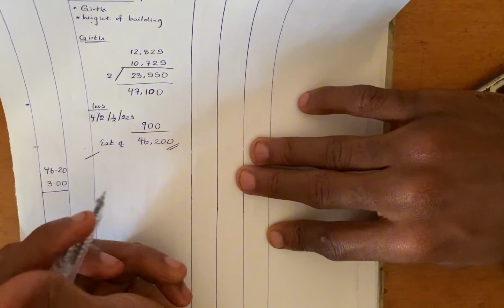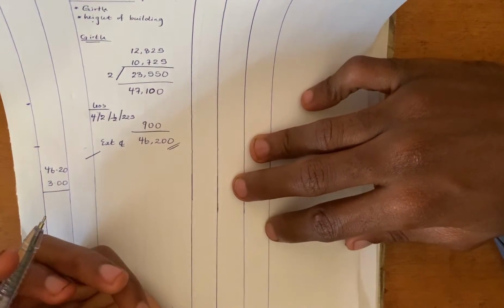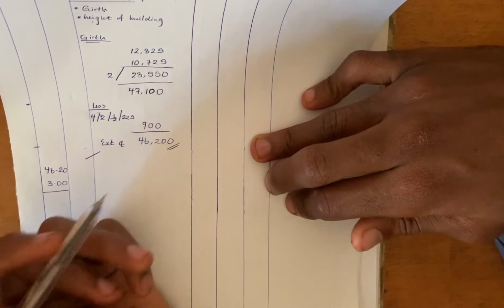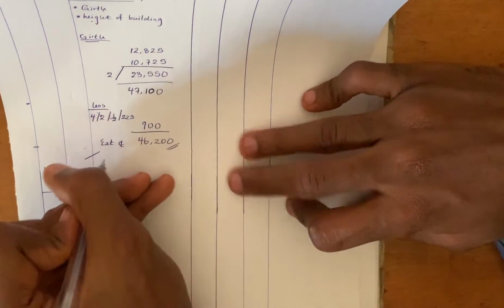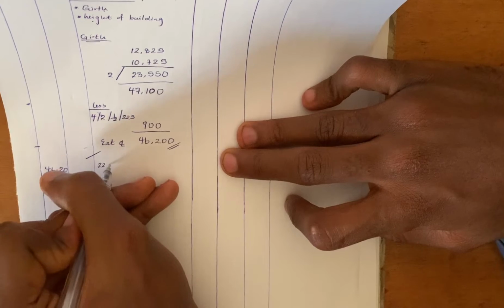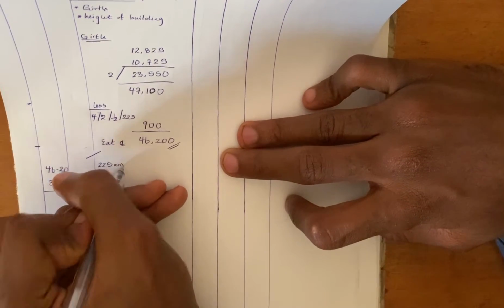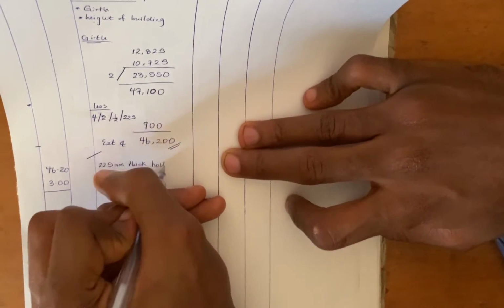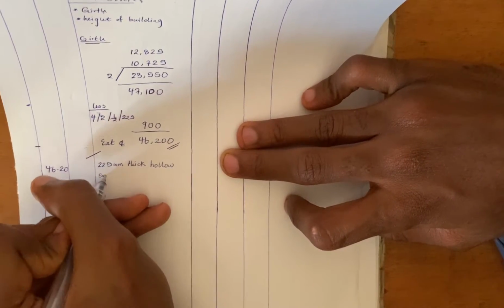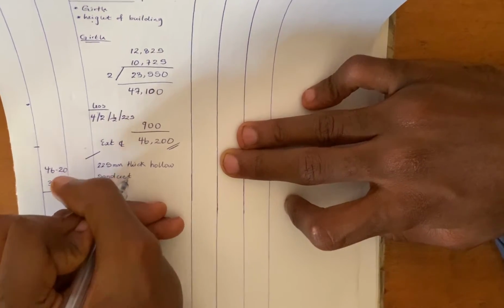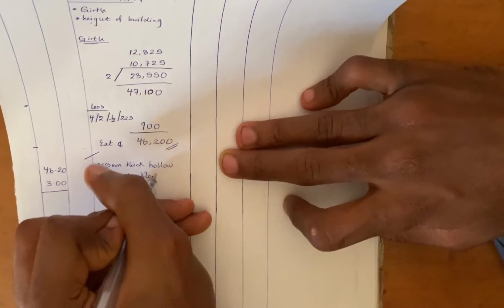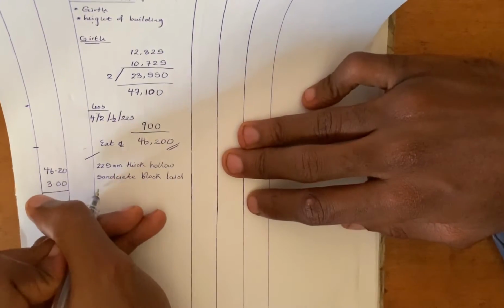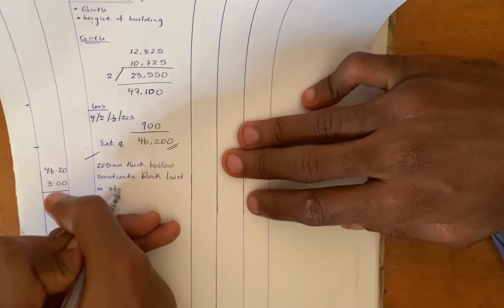How do we describe this? It's easy. What type of block work are you using? Or what type of block are you using? Hollow sandcrete block. What is the size? 225. So you say 225 mm thick hollow sandcrete block laid in stretcher bond